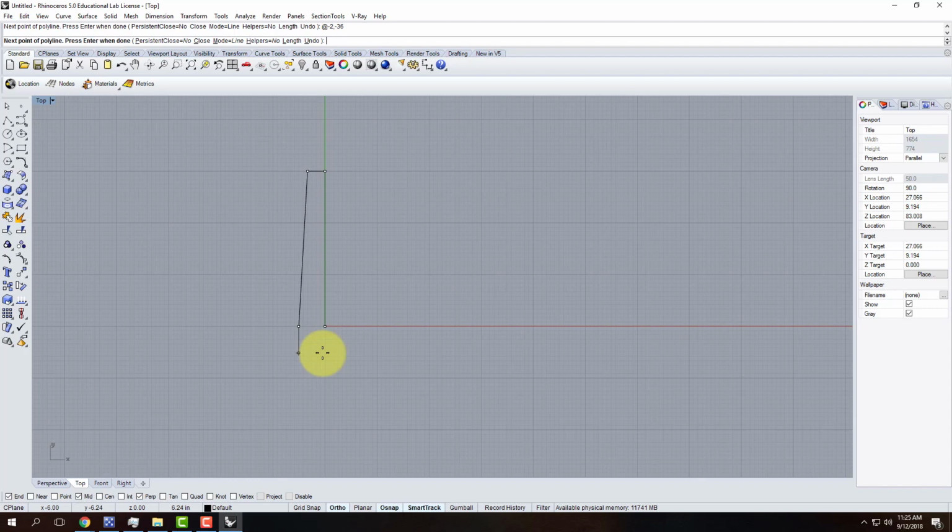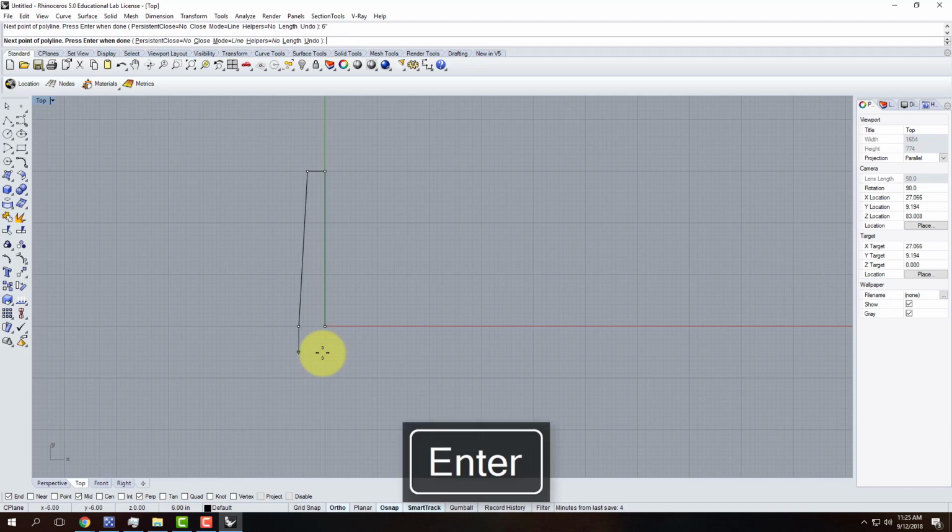So if you're off floating in space, use the relative coordinates, then you don't have to worry about, well, wait a minute, where is it? It's just relative to the last point. So as I continue, I'd go down 6 inches. So that's just distance and direction. There it is. Now this next one, here's another perfect example of using those coordinates.